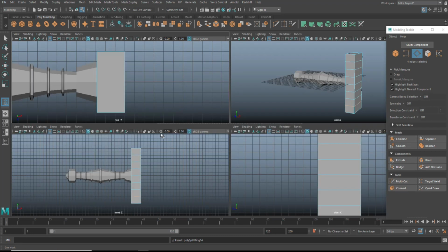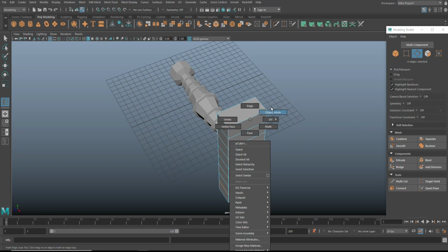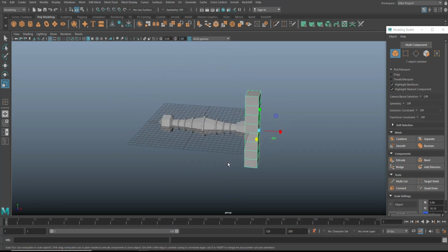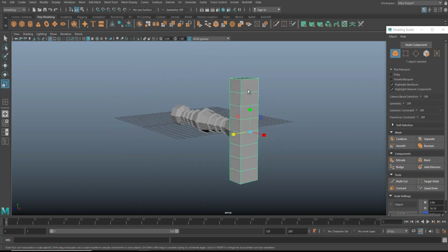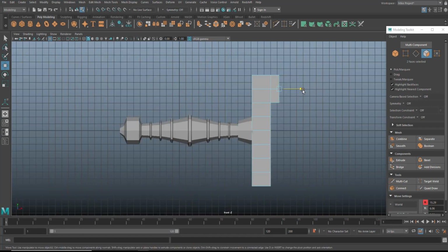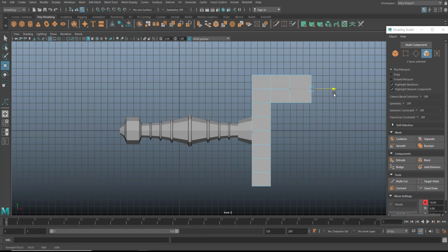And from here, we can then start to bring out the default shape. This is still a bit too thick. Let's bring that in to about there. And then what we're going to do is we're going to go in here. We're going to right click on a face, 1 and 2. Control E to extrude, W to pull out, to about here. G to repeat, W to pull out. And that'd be all right.